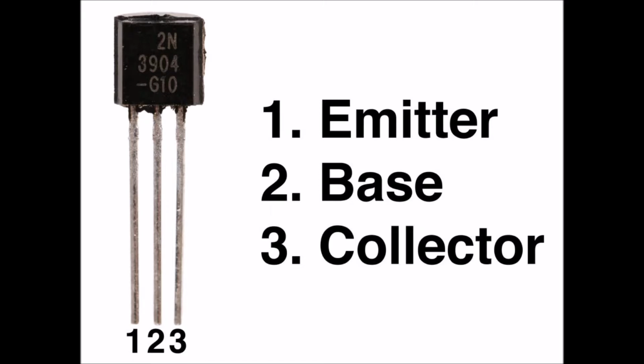Zero bias also prevents any current from flowing between the emitter and the collector, unless we inject an AC signal at the base to change things. Such a signal must at least momentarily attain a positive voltage equal to or greater than the forward breakover voltage of the EB junction. When no current flows between the emitter and the collector in a bipolar transistor under no signal conditions, we say that the device is operating in a state of cutoff.